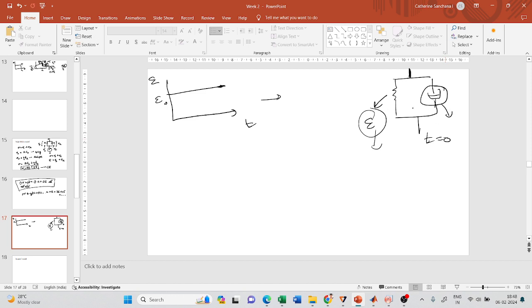So there is an imbalance here, right? The strain here in these two cases has to be the same. But since the dashpot will take time to respond, this Kelvin model cannot give the response of the material when it is subjected to a stress relaxation experiment. Okay, so the Kelvin model cannot serve the purpose of determining the stress response when subjected to a stress relaxation experiment.